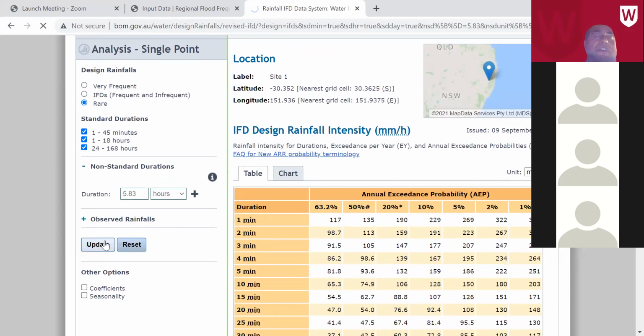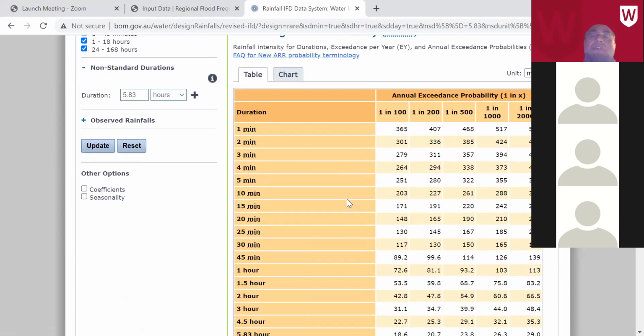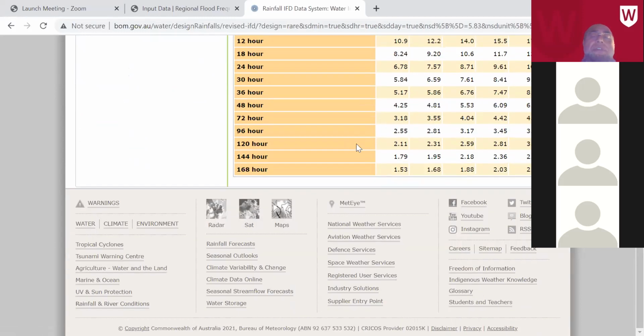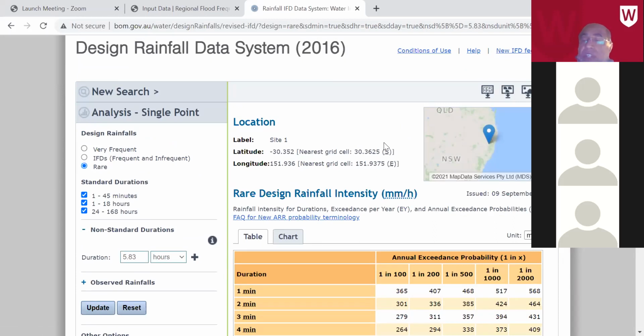And if you go to real rainfall, then you see it's giving up to your 100-year return period to 2000-year return period for different durations. So our Western Sydney University, we assisted the Australian Bureau of Meteorology as well in deriving this IFD data. They gave us some funding, and Khaled and me, we developed some technique for them to do the GLS regression for doing the estimation at all different locations.